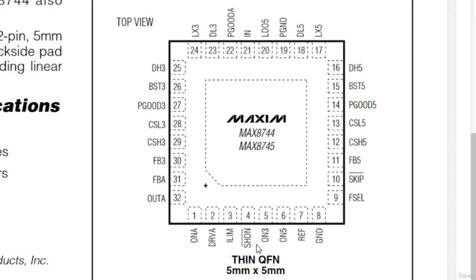As you see, we have here the shutdown. This is an enable signal. If the signal is activated, the IC, or the power management IC, will stop working. We have here ON3, which means enable 3 volts, and here we have ON5, which means enable 5 volts. These two signals are also important. If the signals are absent, the 3 volt and 5 volt will not be generated.